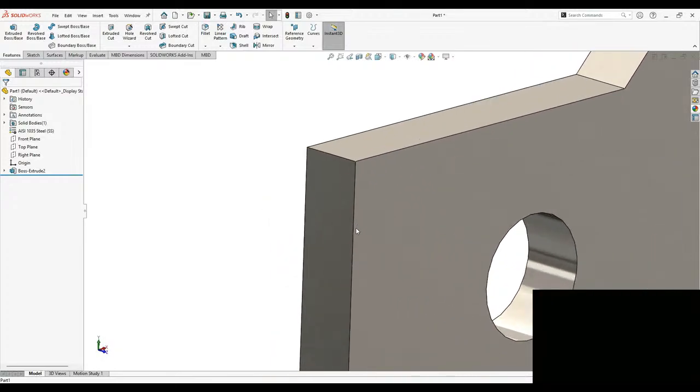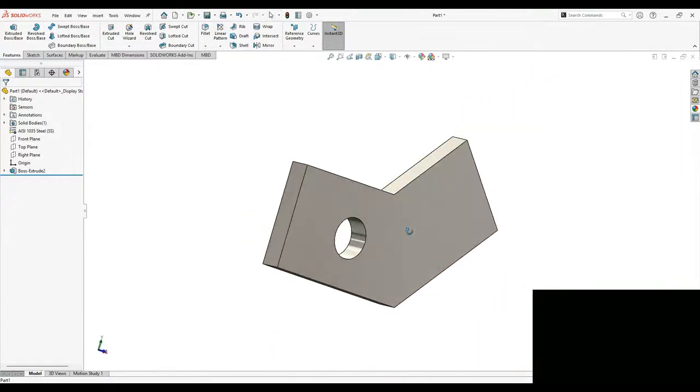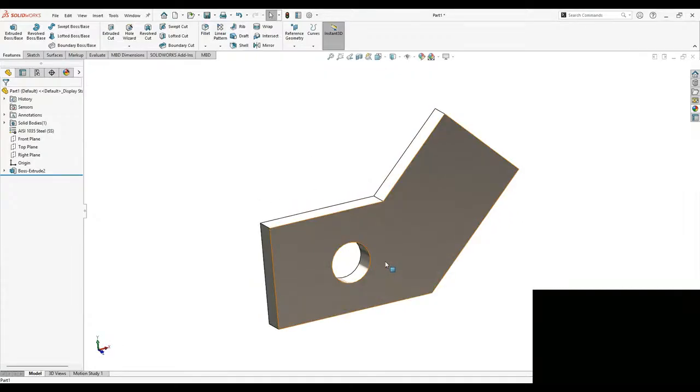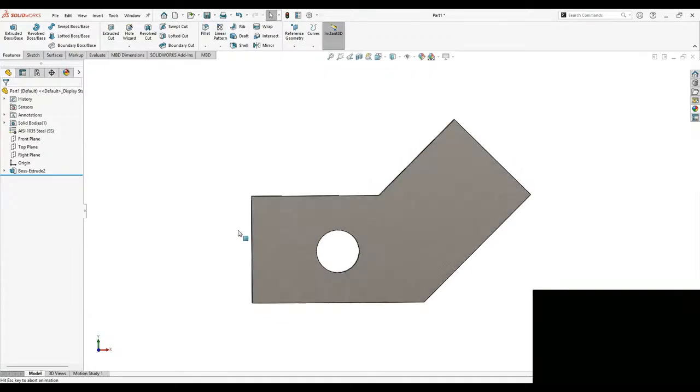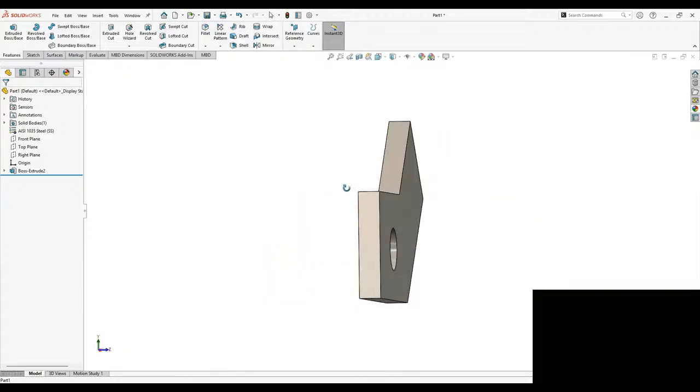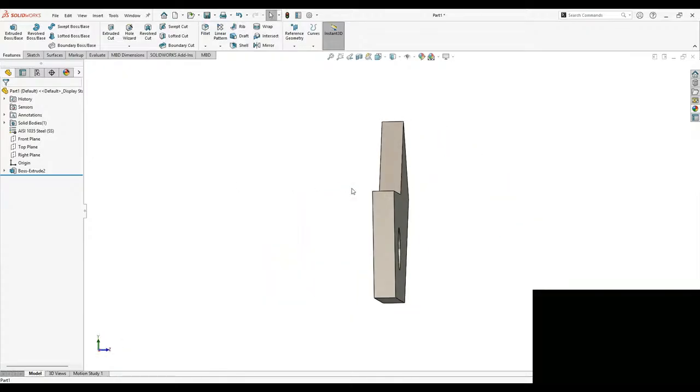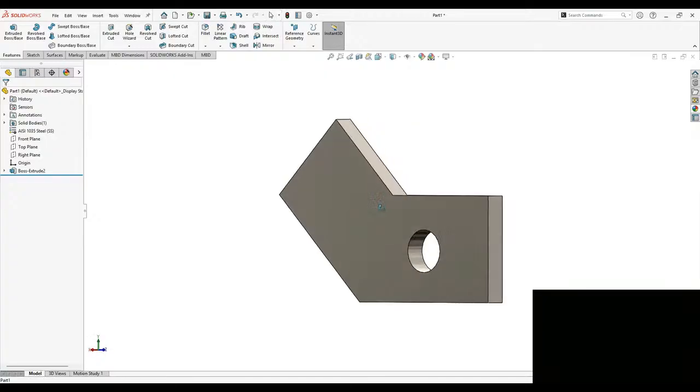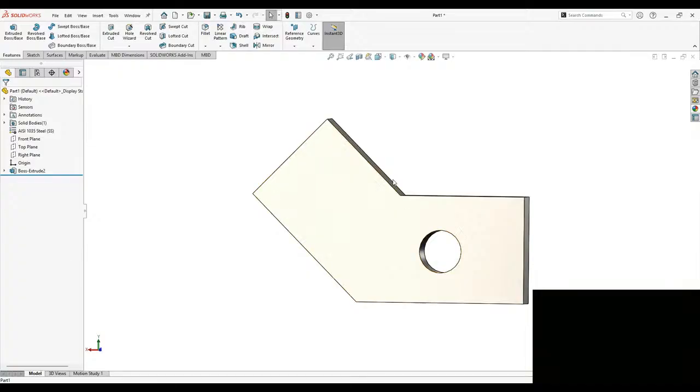Great, right? So if you press I, isometric, it will take the isometric view. Now normal view, right? Advantage of normal view, guys, is so if I rotate like this, now the front view is near, right? If I press N, it will go to the front view. This is the very important thing you need to remember. Normal view is very advanced. So whichever the standard view is near to the graphics, so it will take accordingly.